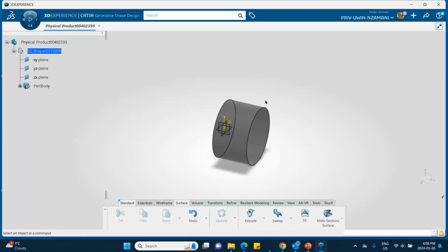Let's apply material to this. We'll make it out of steel, standard properties, because we're going to do linear static analysis. This has nothing to do with whether it's static or dynamic or linear or nonlinear, etc. But because we're looking at the issue of the positive and negative surfaces, we can take the simplest situation.